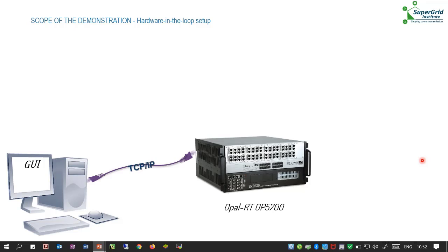So, our workstation and the target communicate via the TCP/IP protocol through an Ethernet cable. It is a bidirectional communication. We can compile the model into the simulation and drive it in real time from the workspace, and receive simulation results from the target via scopes.